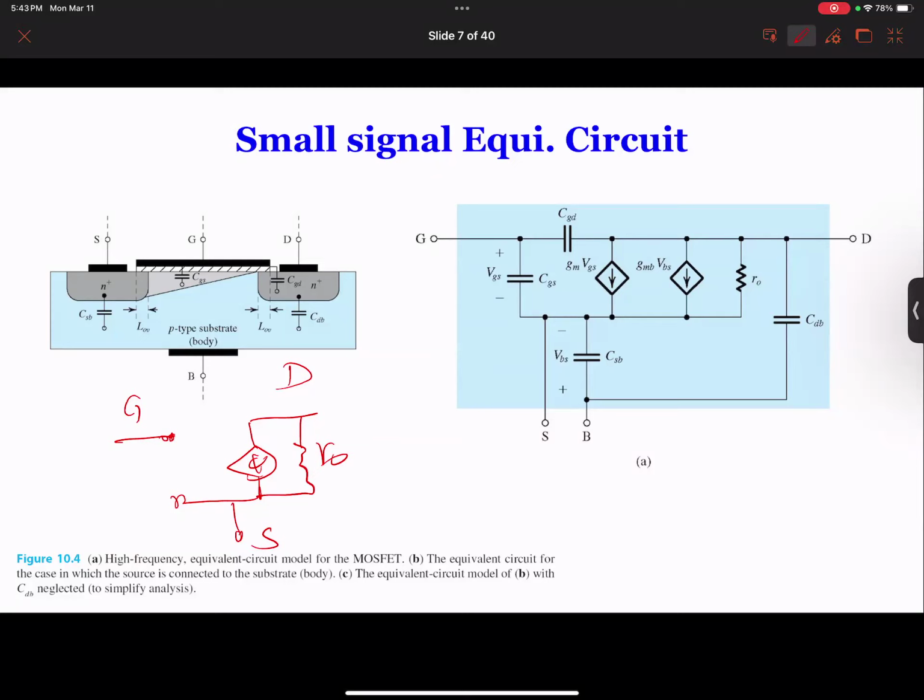So you can see right away, it's no longer open circuit. When we analyzed this before, we always said, this is open circuit, don't worry about it, it's very simple. But now it's no longer because there's a capacitor over here. And then the capacitor between source and the body, right here, we didn't draw the body, but I'll tell you that in this class, basically we can neglect it. But just in case, we know what it is. So between source and body, you have another capacitor. So that's drawn here. And between drain and body, you have another capacitor, drawn here.